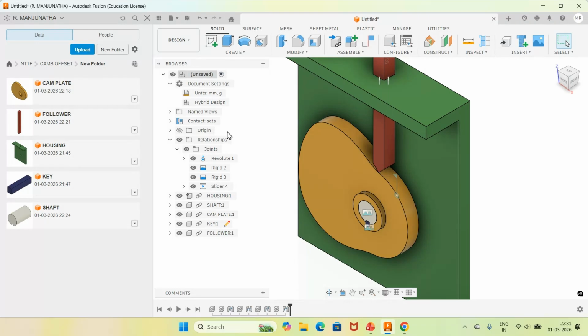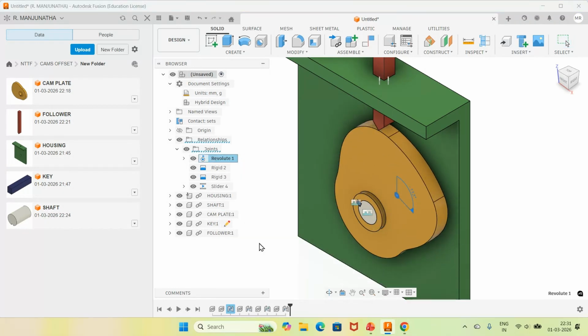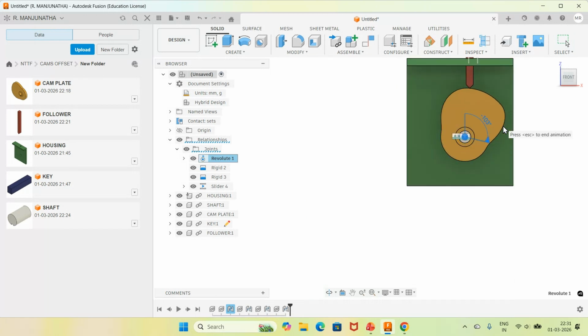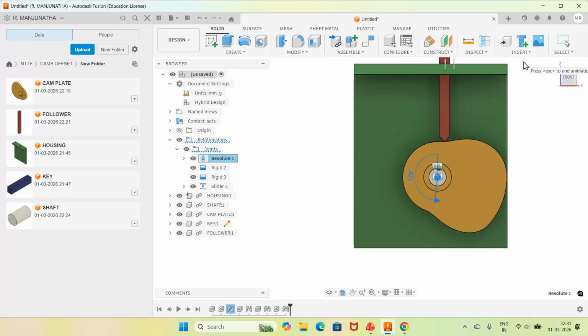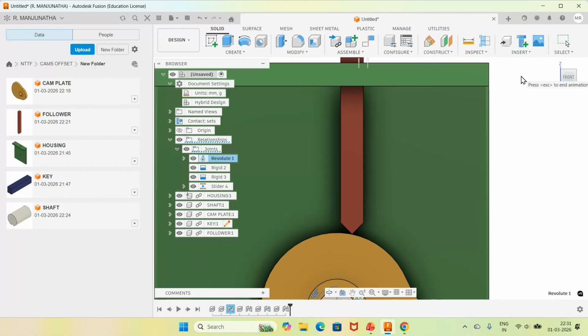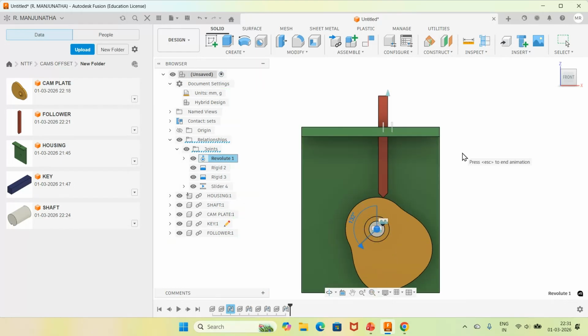Now once you do that, we go for revolute and click on element joint relationship. Now as you see, the motion is taking place in the upper direction, then dwell, outward stroke, outward, dwell, inward, outward, dwell, inward, dwell. So this is how your option will work. So now the next question is, how much is the lift that I need to consider? So this is one part of the animation. The lifting, how it will take, I need to calculate.